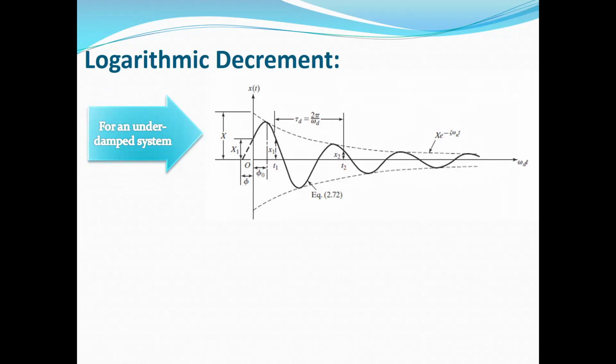You can see we have some graphs like this, because as I mentioned in the explanation for the labs, even when we detach the damper in the equipment in the lab, we still have some damping due to friction and some other reasons. We have some damping, so you can see the same graph like this.